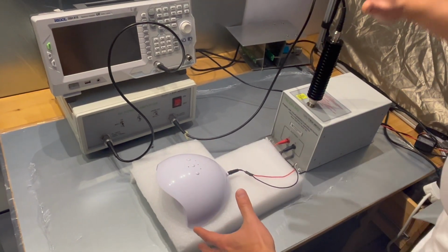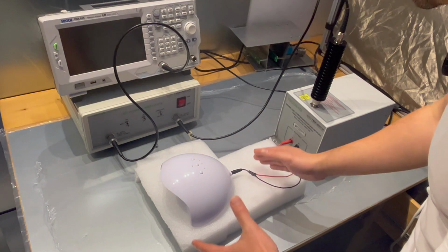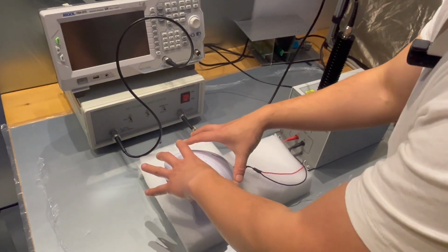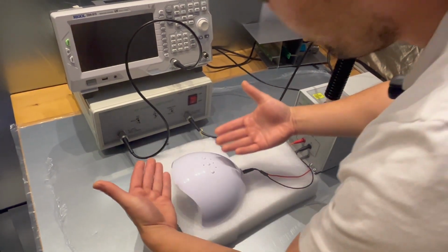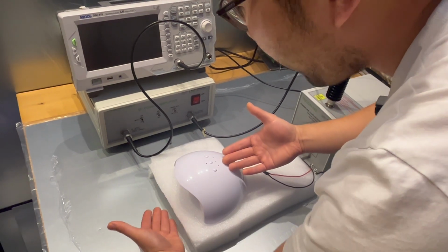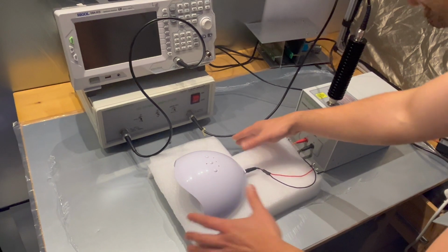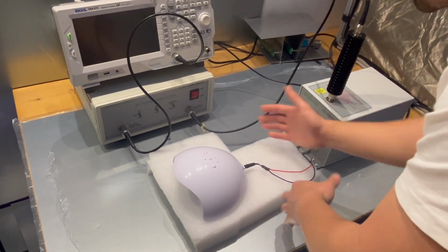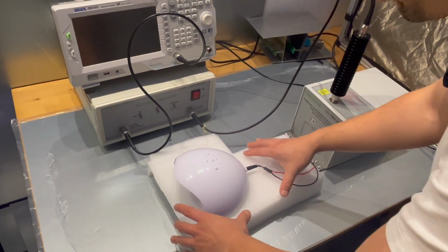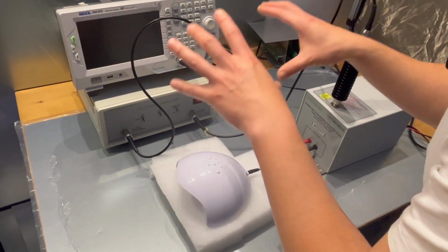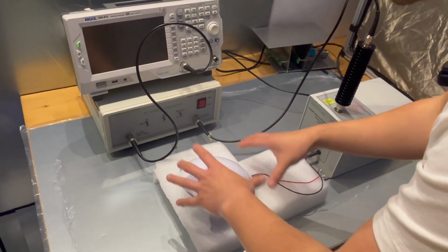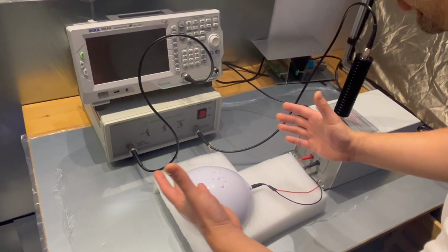Think about it: common mode noise gets injected into the cable structure, arrives at the EUT, and then comes back through that parasitic capacitance. The surface current flows on the test ground plane back to the system. That gives you a defined parasitic capacitance to finish the loop.